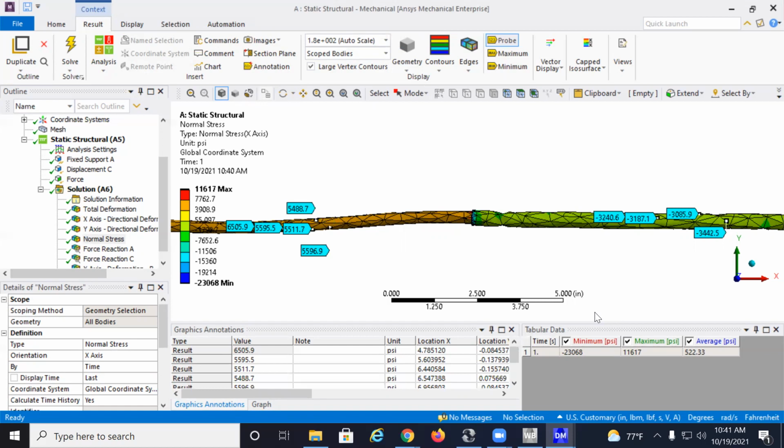But at least we were able to get the result just by using the default mesh. Now, I'm blaming some of the discrepancies on having a mesh that is not very fine. I can show you the effect of the mesh. I don't want you to worry too much about it. For the most part, we can use the automatic mesh generator without having to make changes in this class. But when you practice and you use finite element, you want to make sure you have a good mesh. And in this little example, I'm going to demonstrate the importance of having a fine enough mesh.